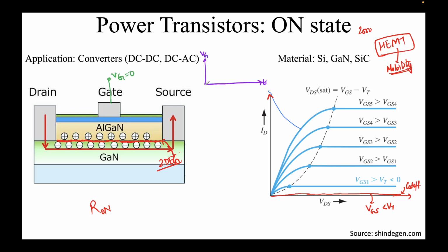So at one point of time you are applying Vg equal to 0 for some time, and then you're turning the device off. So this is -5 volts. Okay. For some time it's off. Then you want to turn it on again, then off, and then on again. So you want to continue this cycle. This is the switching thing that I was talking about, right? So this curve corresponds to Vg equal to 0, correct? And this corresponds to Vg equal to -5 volts. So you want to be switching, as far as ID is concerned, between these two curves.